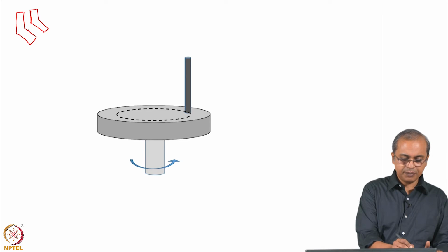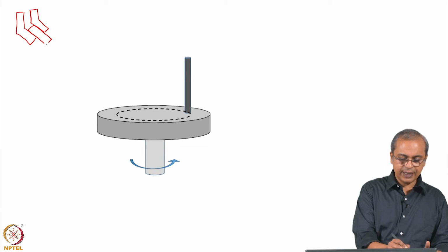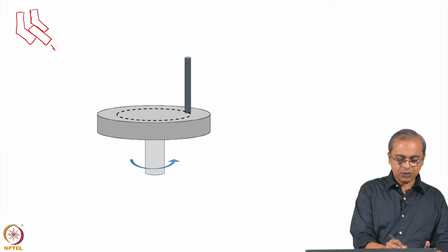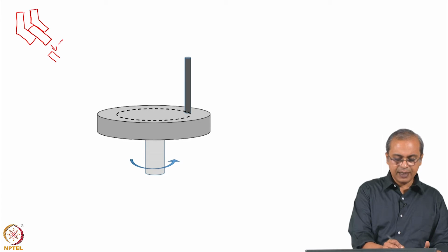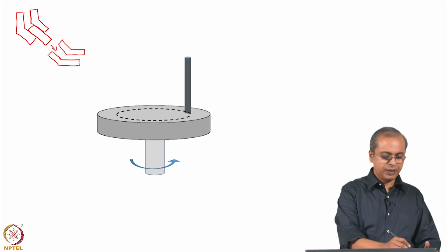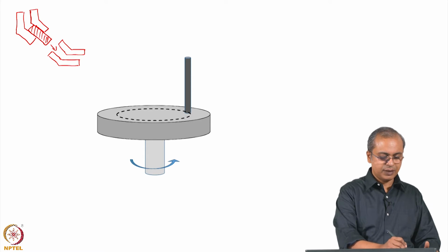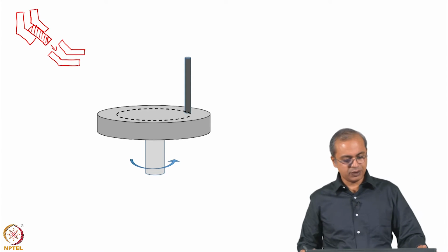And so, the sample that comes out still has the cross section that it originally had, but it has already undergone significant severe plastic deformation, and then you can put it through one more pass like that. So, this is just an example of what you could do. The angles that are there can be changed and various things you can do with it, and that is your sample that you repeatedly send through this process.